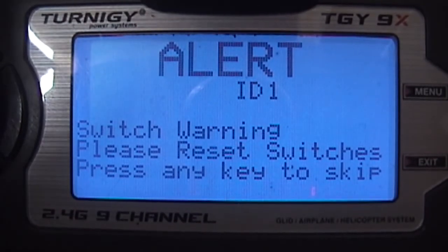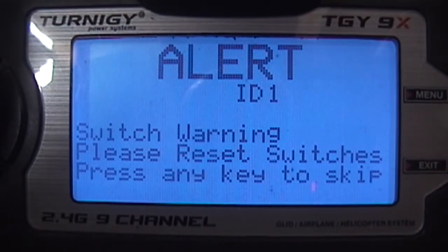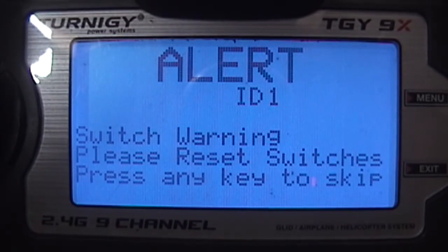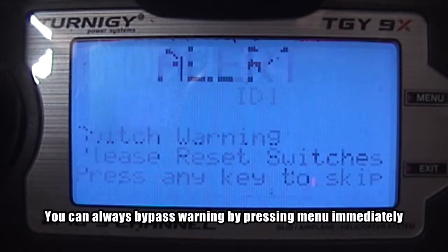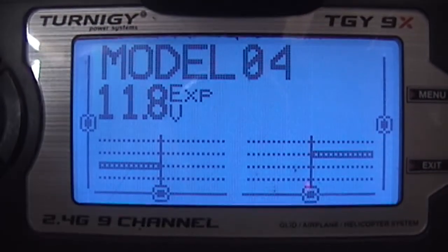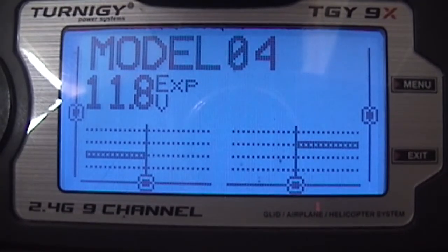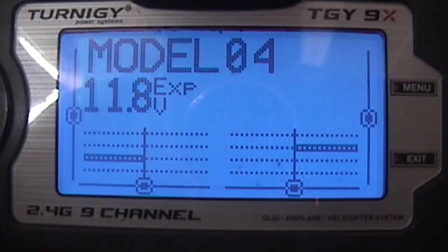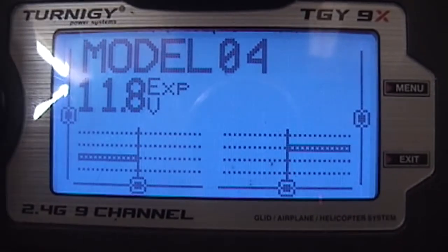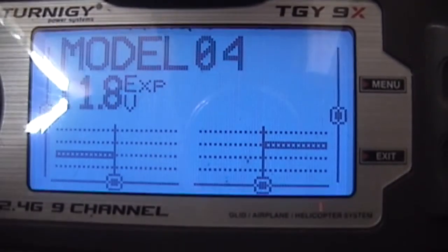No link, unless you switch all the switches back to the default settings. That is up, the three-way switch up, and the gear switch down. And look at the values. At that position, when the radio links with the model, you are in auto circle mode.